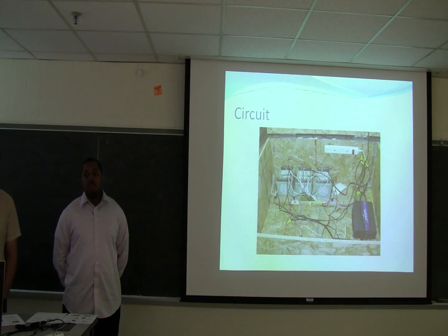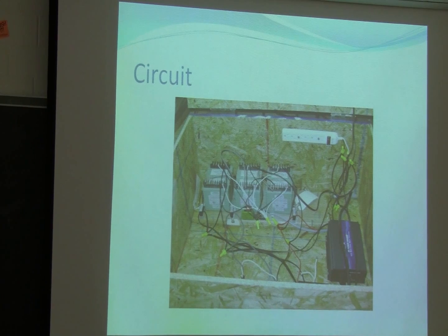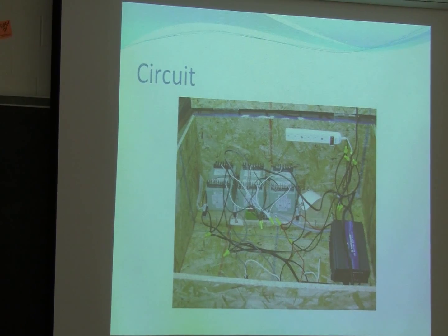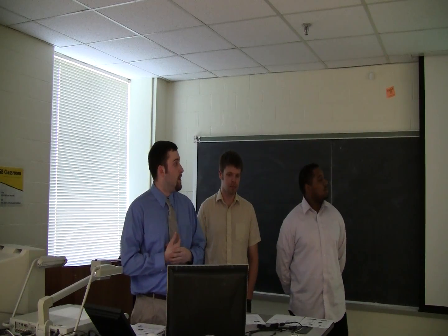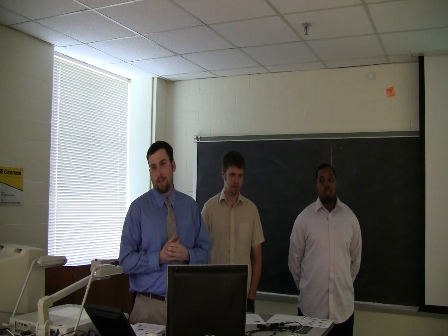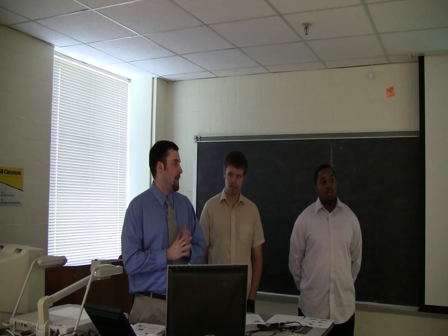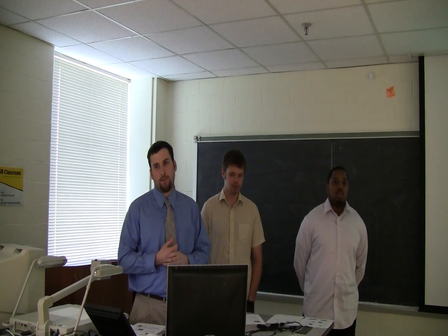This next picture is basically the circuit we have together. The big green mess over there is the transducers. We also have the Hall effect, which we use when we read the current. It goes from about -35 to 35 amps and brings it to plus or minus 10 volts, so we can read it into our acquisition board without damaging the board. Each of the voltage readings can go from about 500 volts down to plus or minus 10. That way we can read anywhere from 120 to 240 volts, depending on what part of the house it is and what appliance you're trying to read the voltage from.